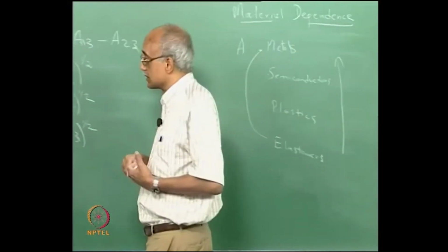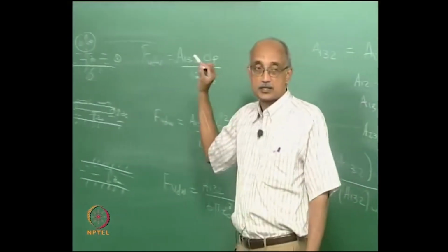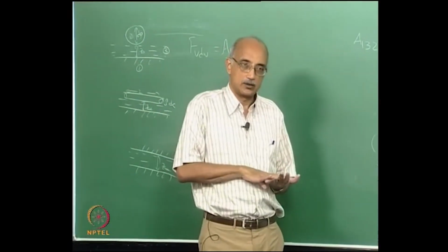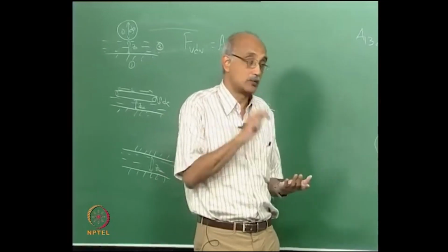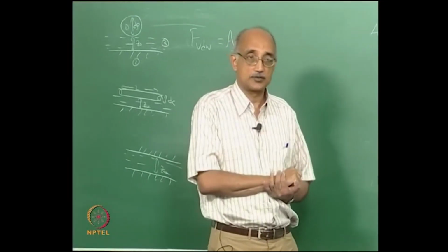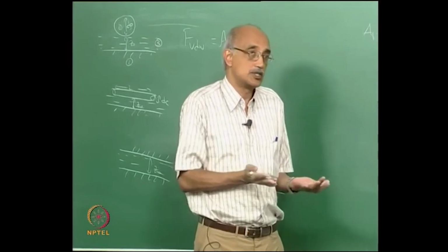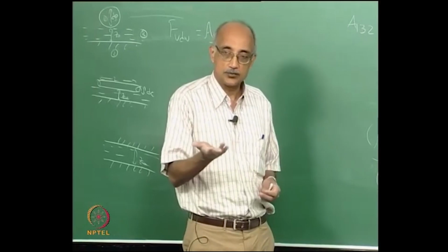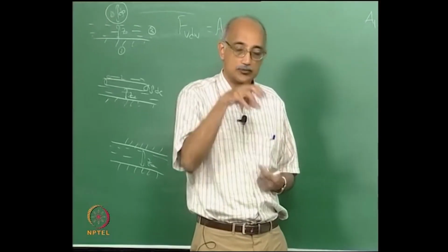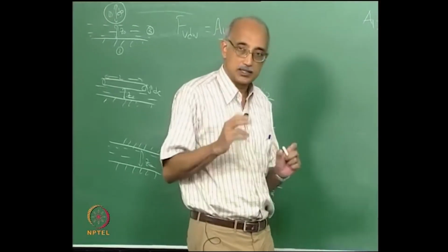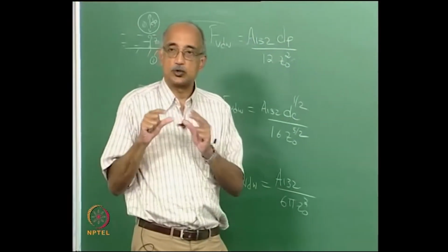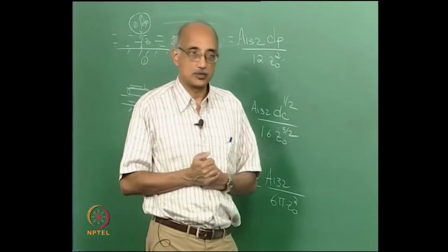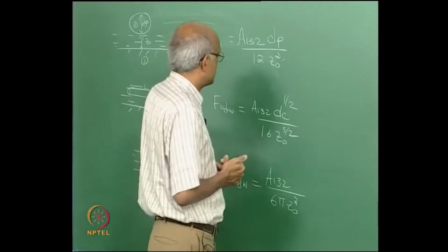Well, one is this Z0 in the denominator, right? As the material deforms, the particle can essentially make much more intimate contact with the surface. So remember, we talked about the equilibrium distance of separation that can drop to virtually 0 when you have a deformable material surface or even a deformable plastic, deformable particle. In both cases, the intimacy of contact between the two approaching surfaces will be much more, which means that the values of Z0 will be much smaller. And the other reason is